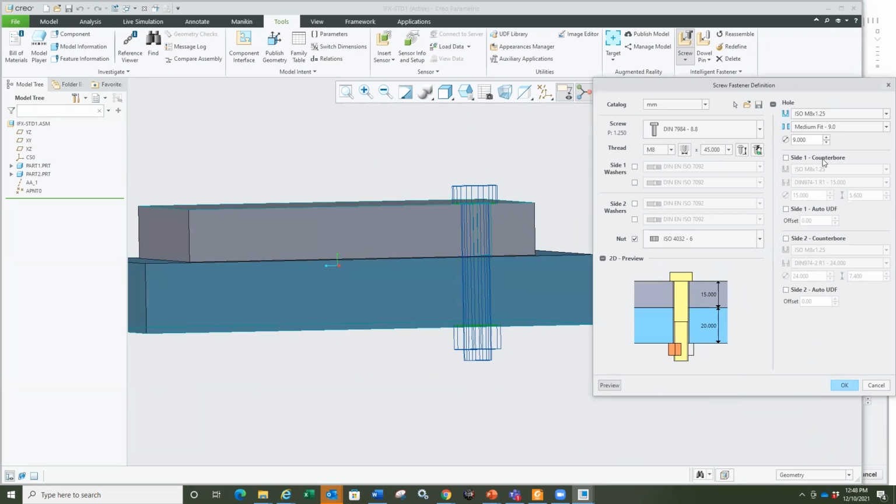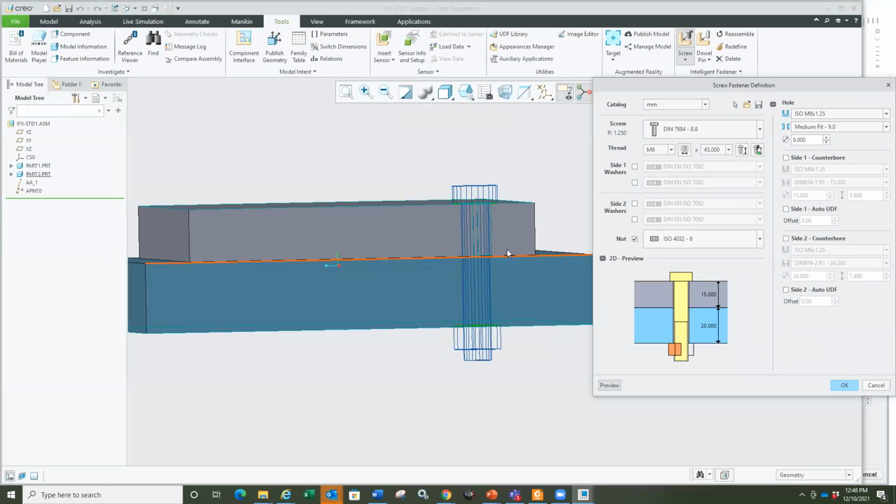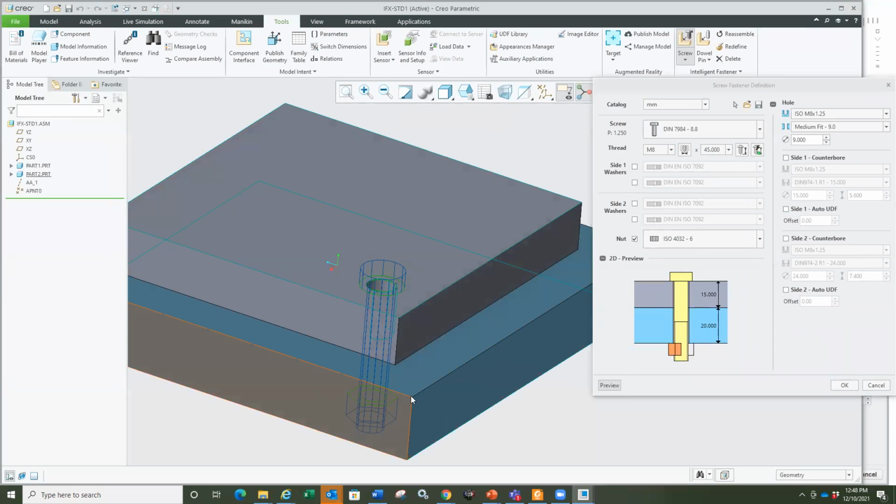And if there is no hole created, I can even have the hole created automatically from the assembly without external reference. That's the key, without external reference. I know you're thinking right now it's an assembly reference, but there was a way to say don't do an external reference, a config option, where it will create the hole using two X and Y planes of the part.